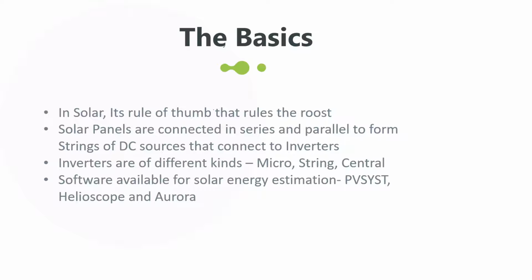So based on these inputs, you are asked to estimate energy. The typical types of solar installations are rooftop commercials, or you also have rooftop residentials, which are very small, typically 5 kilowatt, 7 kilowatt. That's residential, whereas commercial goes up to 400 kilowatt to 1 megawatt even. Well, beyond 5 megawatt is usually ground mount.